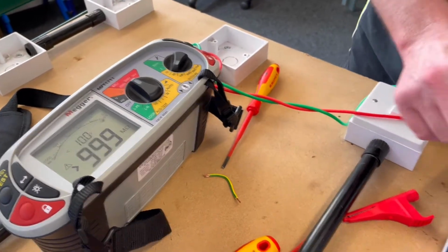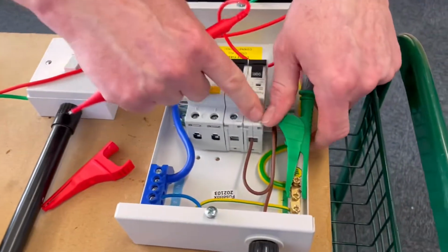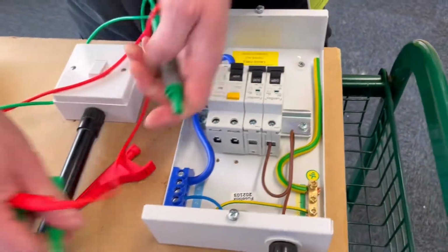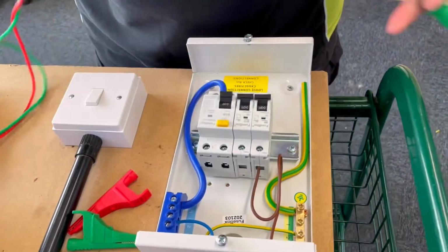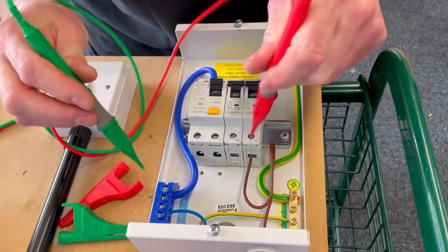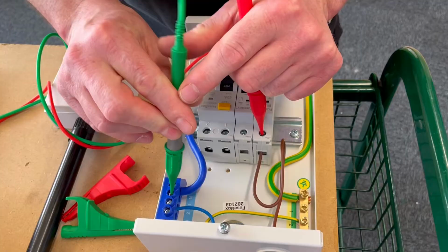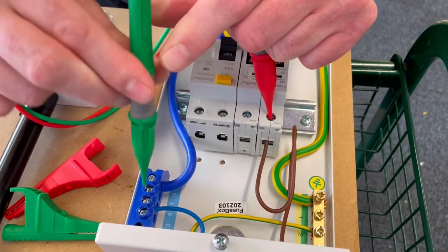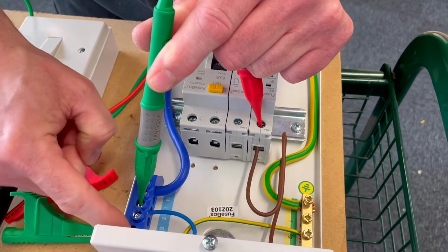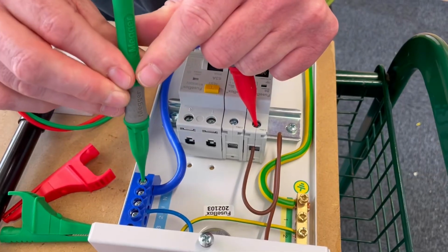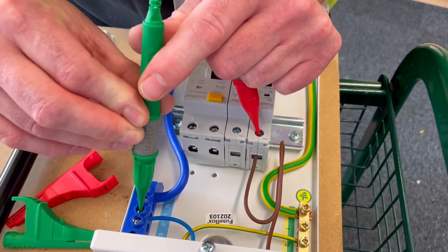And then finally, we need to test between the line and the neutral. Again, it doesn't matter which way around your test leads go. So I'm going to test on the line connection and where the neutral is. Again, it wouldn't matter where I go. So I know that's the terminal I'm testing, and people get obsessed with putting it on top of there. This is a solid bar, so it wouldn't matter where I probed onto. So I'm in those positions there.